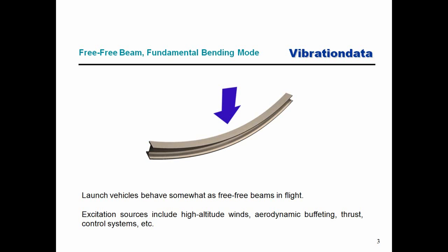And then once the launch vehicle flies, then we do our post-flight data reduction, and we have to determine what the measured natural frequencies were for the bending modes, or there could be more than one bending mode excited. Then we need to close the loop, and we need to go back to the guidance and control engineers and say, well, here's what we predicted ahead of time, which we already gave you. Now here's what actually happened in the flight.